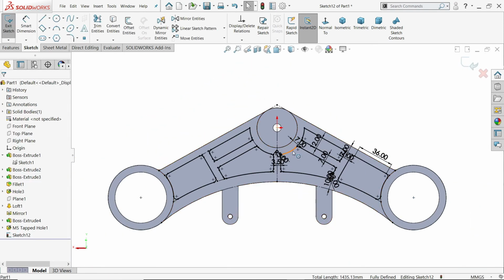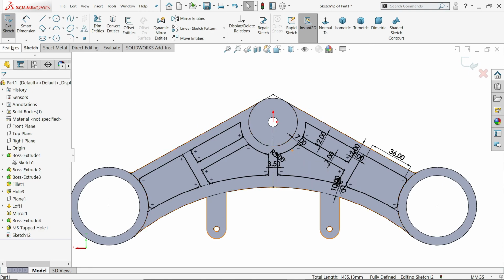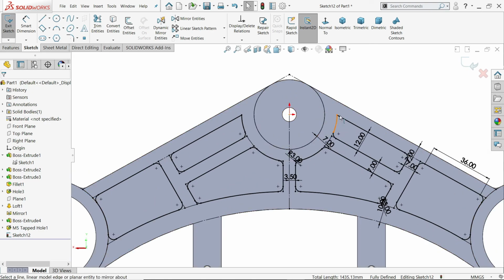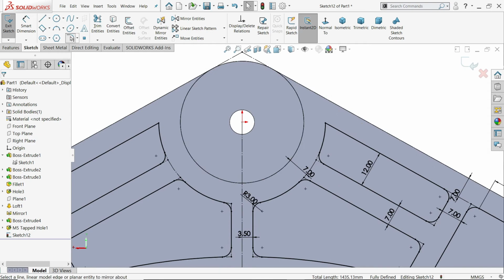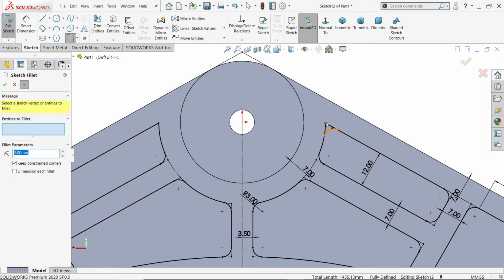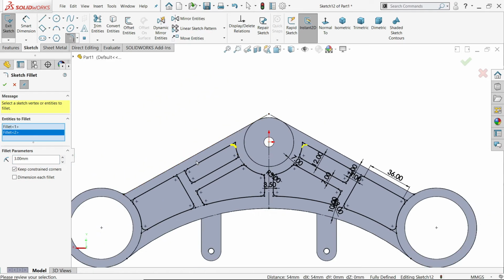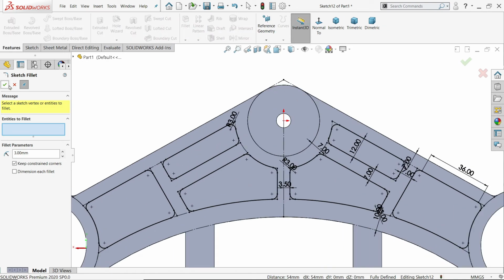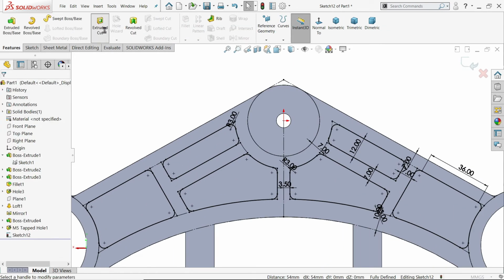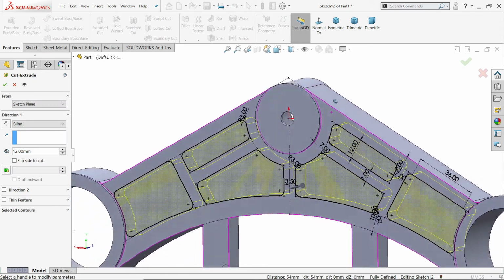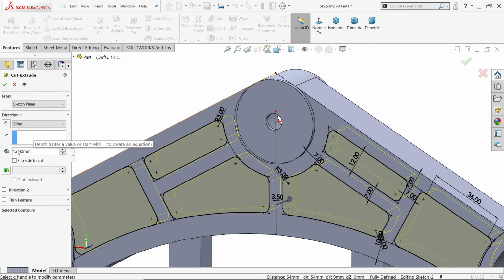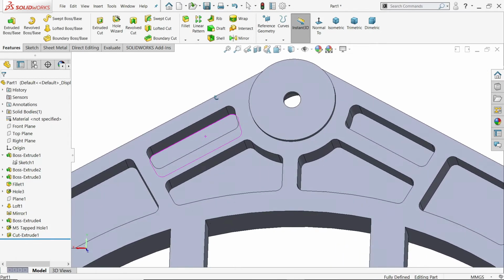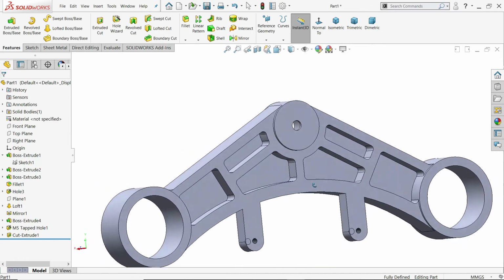Okay. Now this is a fully defined sketch. If you find something, okay, corner radius 3 millimeter. Let's choose this one here. Say okay. Now activate the extruded cut tool. You will see it's automatically selected. Keep end condition 12 blind. Say yes. Look how we created the backside.